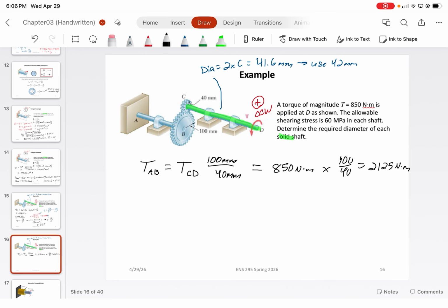So in this case, the total force is around 21,250 newtons. And that just comes from F teeth being equal to 2,125 Newton meters divided by 0.1 meters. That's just the force through the teeth, in case you were interested.